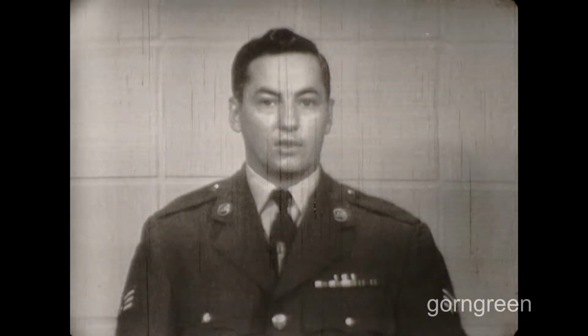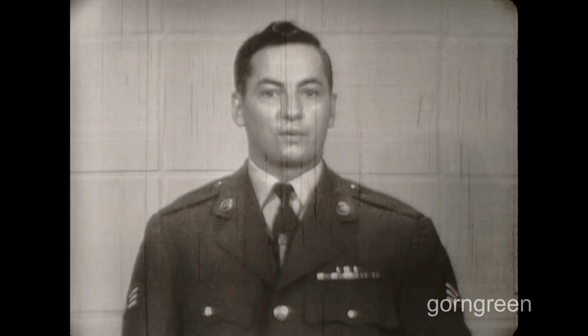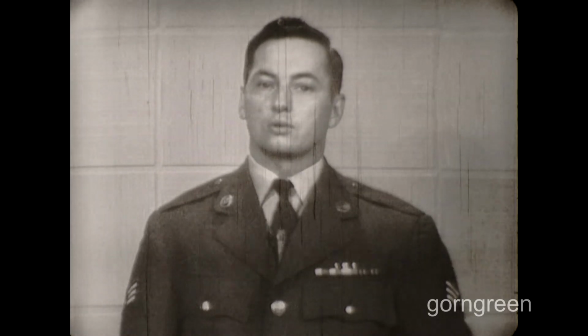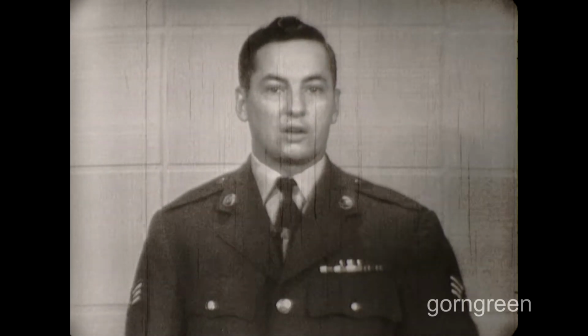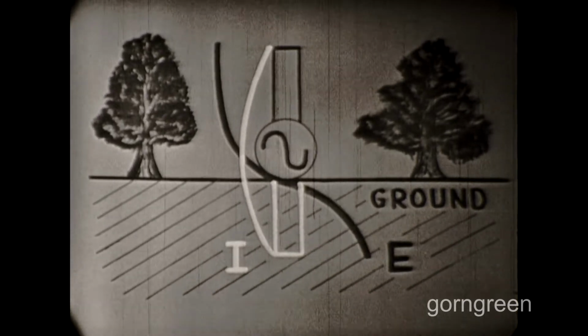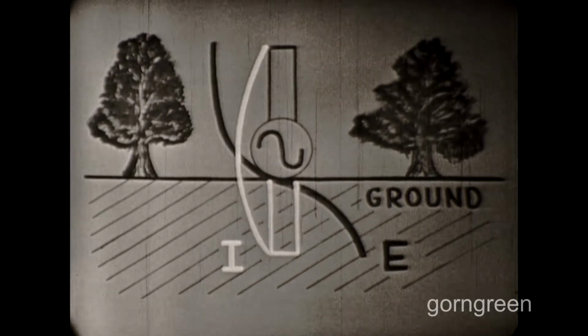According to his theory, the quarter wavelength radiating element will radiate the energy, and the ground will act as the other half of the antenna, so it will retain its half-wave characteristics. And his theory must work because commercial radio broadcast stations all over the world are using grounded quarter-wave antennas to broadcast their programs. Here's what actually happens when you cut the half-wave antenna in half and ground one end of it.